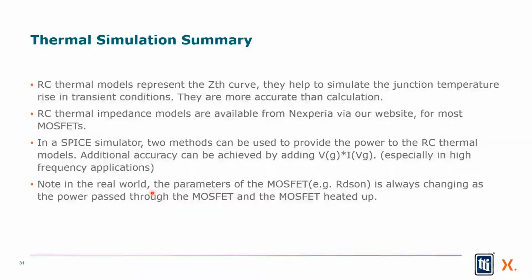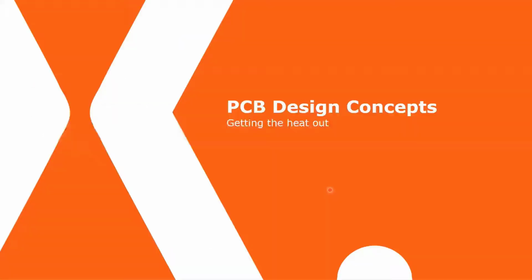If you start getting out near the edges of destruction, you need to be very careful about my own self-heating, because the RDS(on) has gone up, which is now modifying my equations. But again, that occurs out at the edges. There is new modeling work coming out, which someday will let us compensate for that as well. But just for brute force simulation, you can always take the simple tool which is available, and based on that, you're ready to go out and do a simulation of your system before you actually build it.